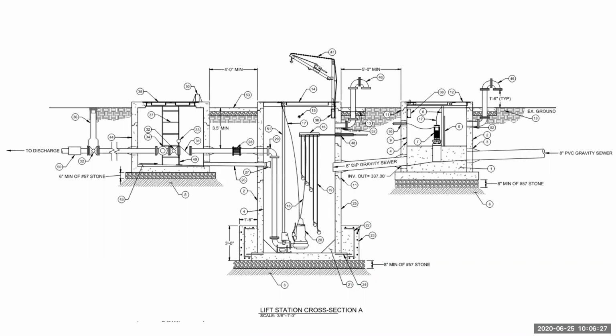So looking at a pump station, this is a section of one of our designs. The major components to note, obviously you've got your gravity sewer coming in, and this structure here is the wet well. Inside the wet well, in this case, you've got the pump. We call this a submersible style station because the pump typically stays submerged in the wastewater. From the pump, you have your force main. Also inside the wet well, you've got your pump controls.